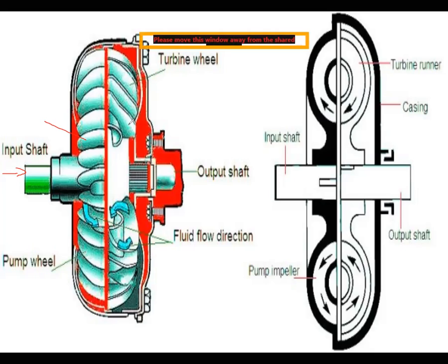That means the transmission shaft. That is the working principle here. The fluid passes along the impellers and strikes the turbine blades. Then again it comes back to the impellers, then again goes to the turbine blades. So continuously it takes a number of spiral, circular cycles in the housing, making the input and output speed constant. Then the power is transmitted. That is the working principle here.